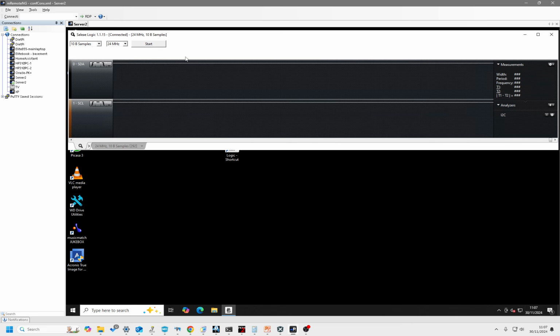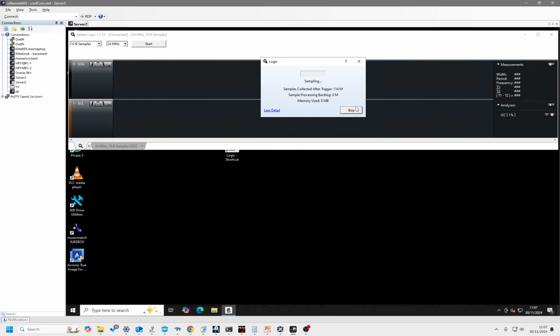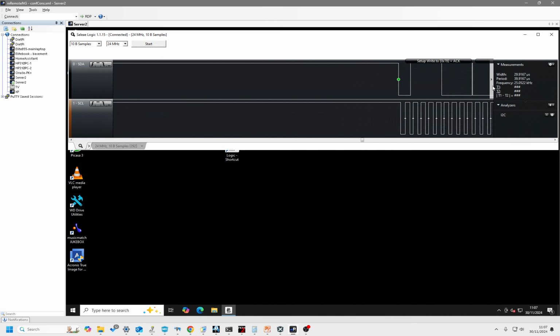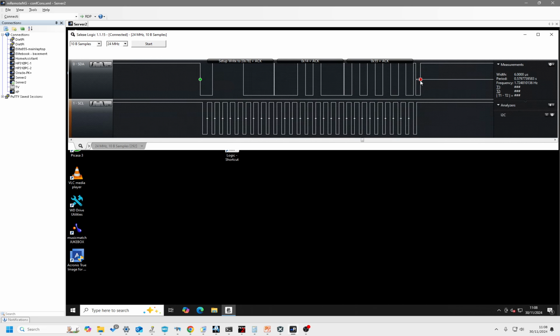Yep. I have another way of resetting the board. Blank check. There we go. Now, all that struggling was just to reset the chip, okay? But we can see that it's moved on to hexadecimal 14. I'll do that in decimal for you there. So we know we're on build 20. Good technique, eh? And here's my 55. And here's my end. My frequency is exactly 100 kilohertz. So I know I have a solution I can build upon.